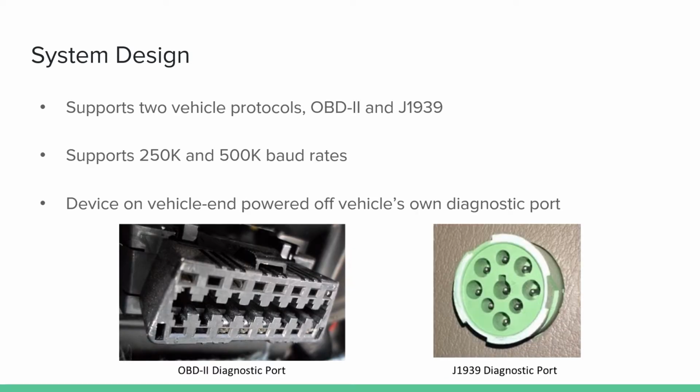Our system also supports both the OBD2 protocol used in smaller trucks and the J1939 protocol used in larger ones. It also supports 250K and 500K baud rates for maximum compatibility with different manufacturers. Finally, the device used in the truck can be powered directly off of the vehicle's own diagnostic port. No need for an external power supply. Next, we'll show you guys a video of the setup and a quick demo.